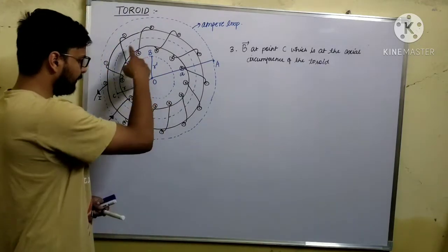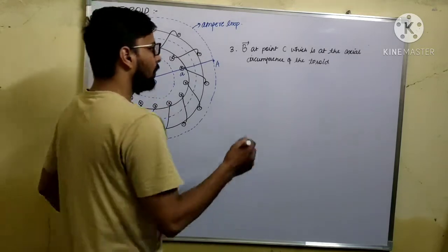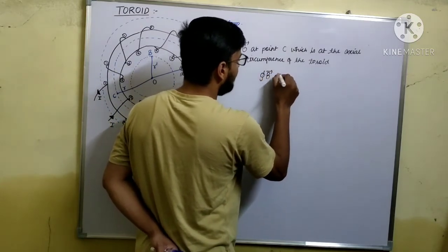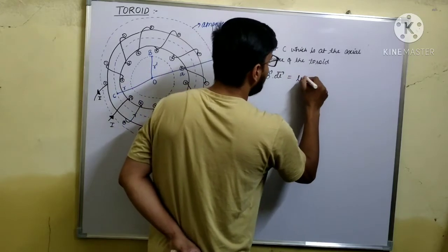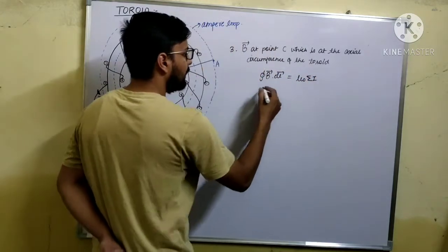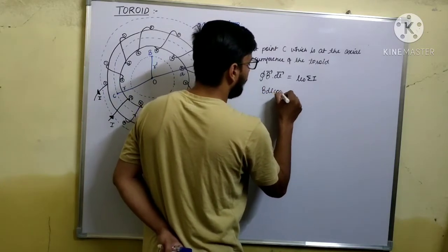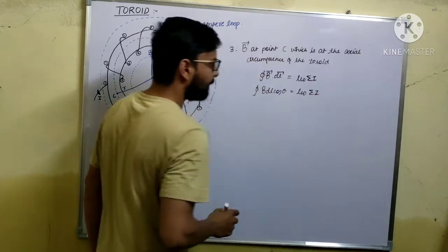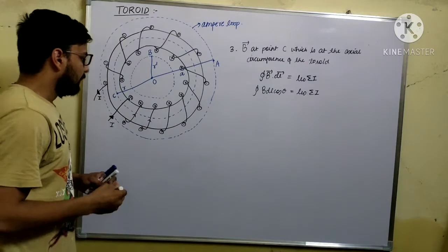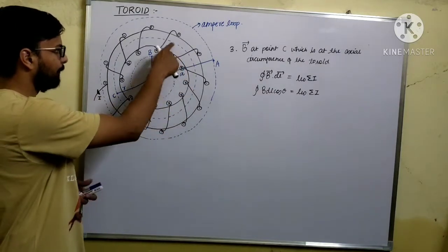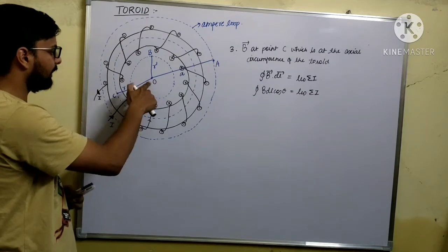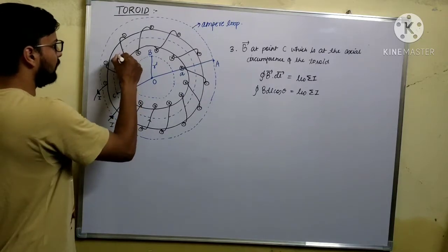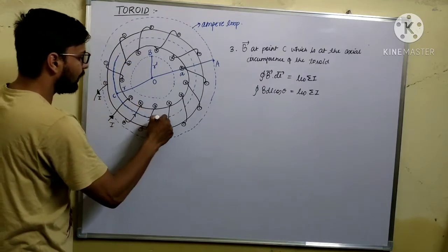So since we form an Ampere loop, we will talk about the Ampere circuital law. So by applying Ampere circuital law, that is line integration of B dot dl is equal to mu naught times summation of current. Okay, so if we solve this further, we get B dl cos theta is equal to mu naught times current I. Now you see that this loop is what? At distance OC, at a distance r, this loop, we are talking about this loop. I will draw it with solid lines for better understanding. We are talking about this loop.